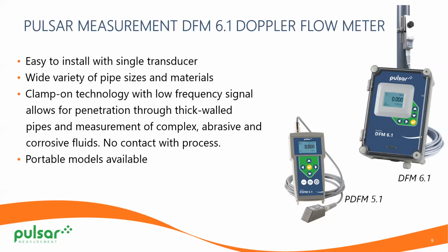And since we're sending that signal at a low frequency, we can still penetrate that pipe wall and get into the process fluid and also have it returned. So it's really designed for nasty applications that can be abrasive, anything that's abrasive or corrosive. Since we're not coming into contact with the process fluid, we don't have to worry about that.